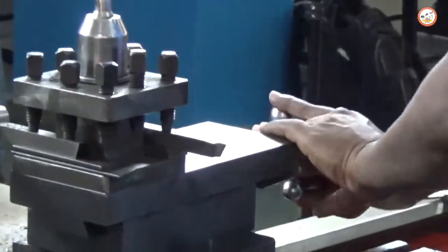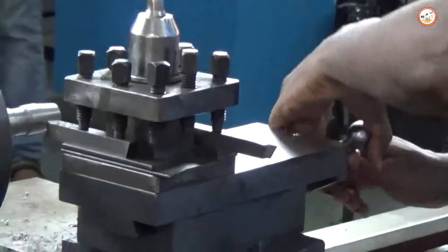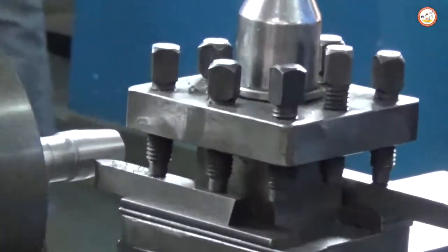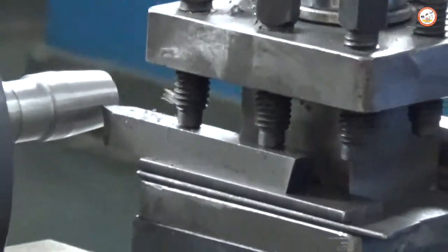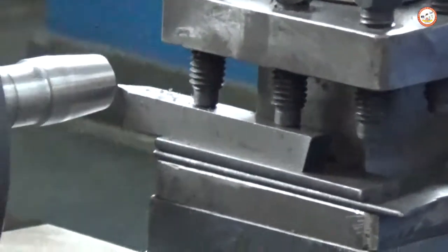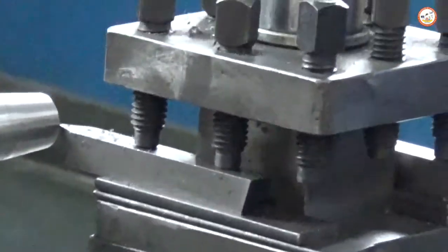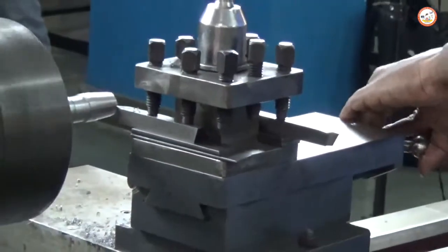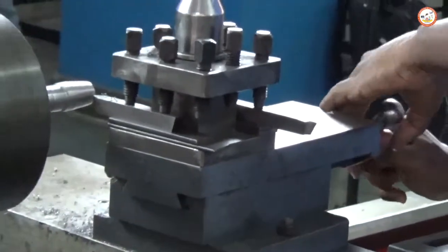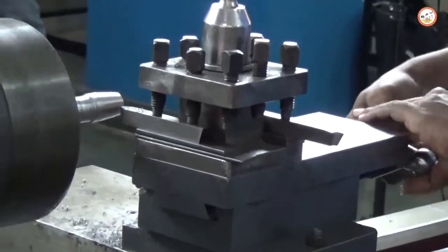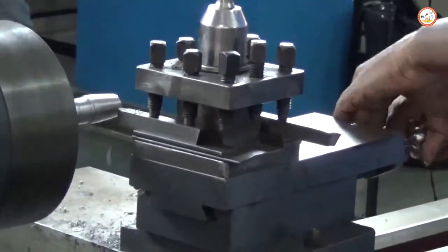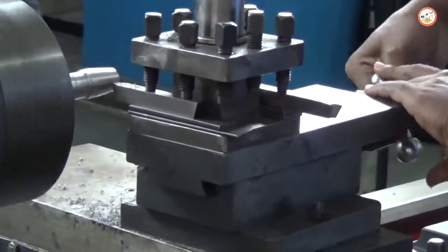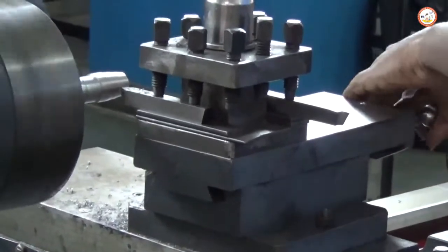We can observe the change in the diameter from one end to the other end. There is a uniform diametrical reduction from the live center towards the dead center. Increase in the depth of cut will lead to chattering of the workpiece. The surface will have irregularities. So, with a small depth of cut, by adjusting as 0.1, 0.2, we will get a good surface finish.